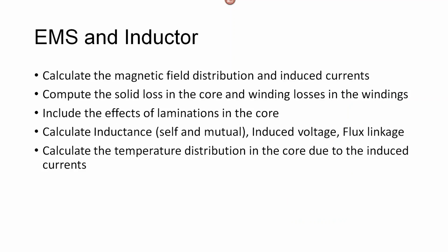Now, why EMS? Why is it an ideal tool or software that you can use to design and study the performance of your inductors? Number one, EMS can help you calculate the magnetic field distribution, the induced currents, etc., inside your model. And with respect to the solid losses in the core and the winding losses in the winding, EMS will be able to calculate those as well. Now you can include the effects of laminations in the core in your solution, so that makes it a lot more real life, and you can solve a lot of real life inductors which include laminated cores.